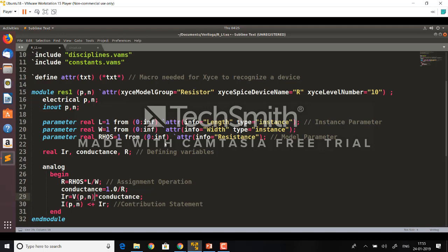I can obviously do mixed mode. I can simply use that Silvaco TCAD and make a circuit out of it. Maybe it will take 10 days to run, because if I have even maybe 10 transistors, it will take quite a long amount of time. It's extremely slow. So what you can do is, if you know how a FinFET works, if you know the equations of a FinFET, you can simply write them down here.